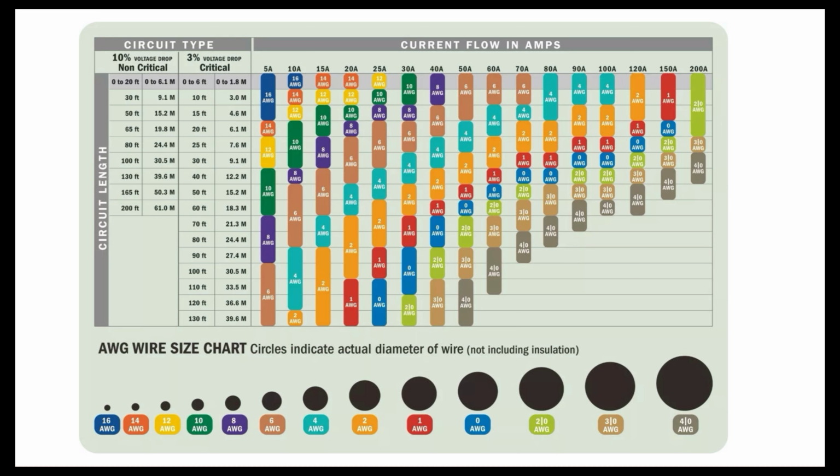Now, you've probably heard of 0 gauge, which is typically used for this big thick stuff, which is used for the power supply for your amplifiers, and that's good up to about 150 amps. But there are bigger wire gauges than 0 gauge. There is 00, 000, 0000, in which case, the bigger the number of zeros, the bigger the wire gauge.